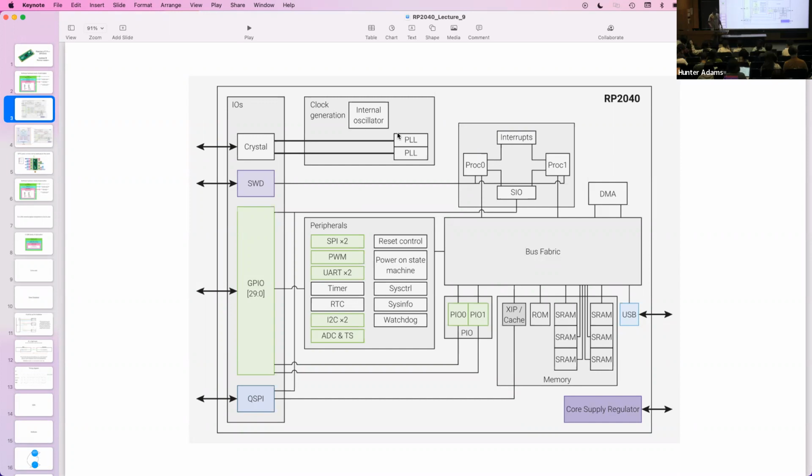But what's fascinating about them is every one of those instructions has guaranteed single cycle execution, and these PIO coprocessors can talk to all of the GPIO ports. And they can talk to things like the DMA channels. So what this enables, as we'll talk about in just a little bit more time, is it allows for you to build custom high-speed communication interfaces. This, for example, is what facilitates our communication with the VGA screen. As some of you might be aware, to communicate with the VGA screen, the clock line for that interface is 25 megahertz, just really fast.